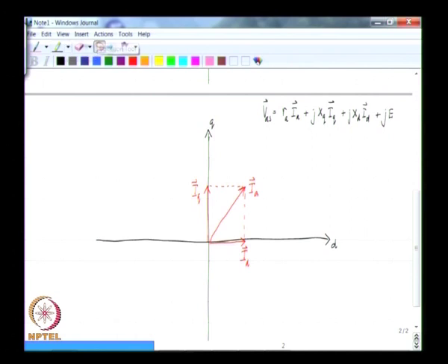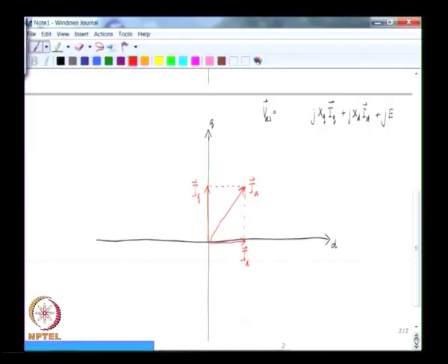We have neglected the armature resistance and therefore, this term is not there. The induced voltage or the stator voltage consists of these three terms now, and we have already drawn the IA phasor. So, J times XQ IQ would then be, well, let us draw the phasor of E first. So, you have the induced EMF E,